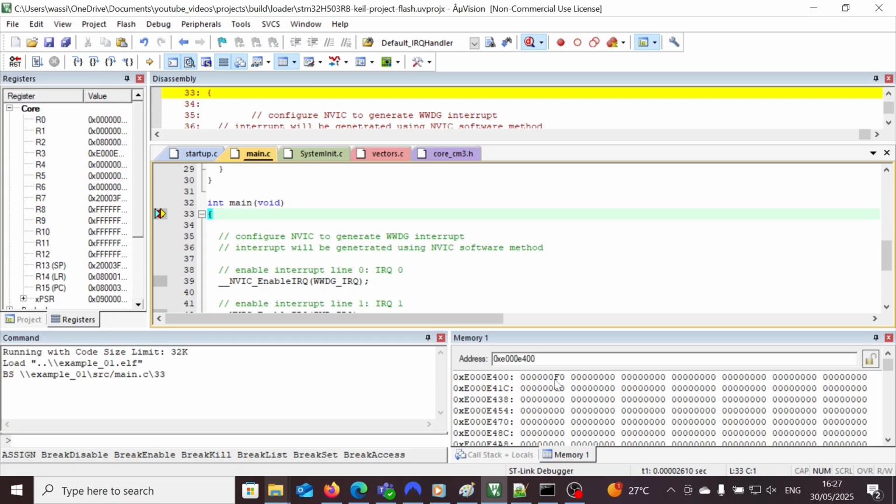In general, as stated before, we cannot have support for 255 priority levels. In most cases, some bits are implemented and used to define the different priority levels, and some bits are not implemented. When we say 4 bits, 5 bits, or 6 bits of priority, we mean the MSB ones, not the LSBs.